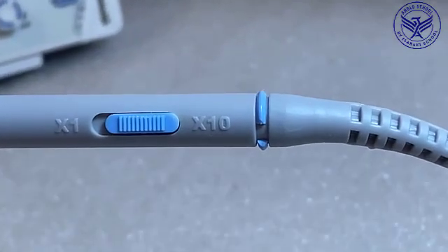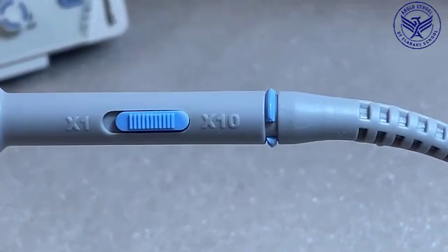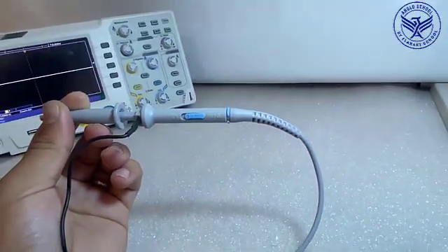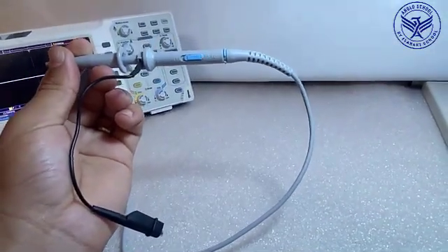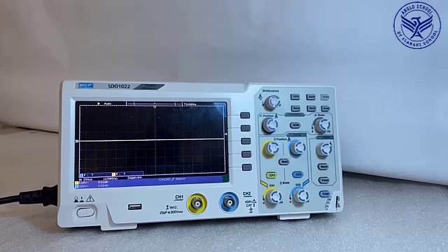However, that does mean we need to tell the oscilloscope that we're using a 10x probe, and we need to tune the compensation capacitor inside the probe. You'll likely only need to tune your probe once, but it's a good idea to check them every now and then to make sure that the compensation capacitor didn't get adjusted by your lab partner or some spooky ghosts.